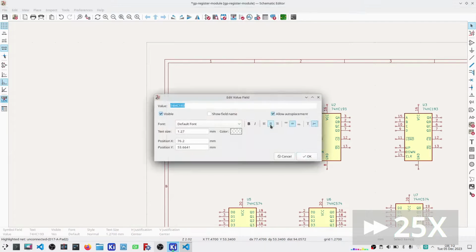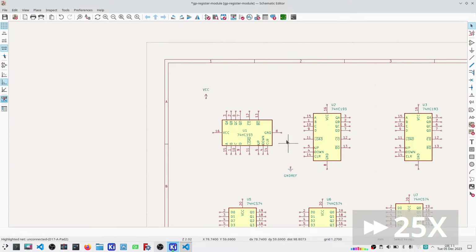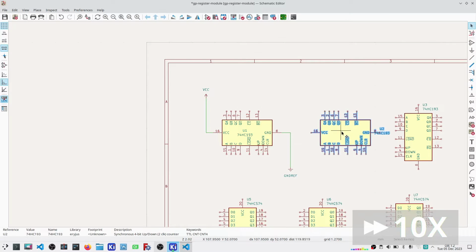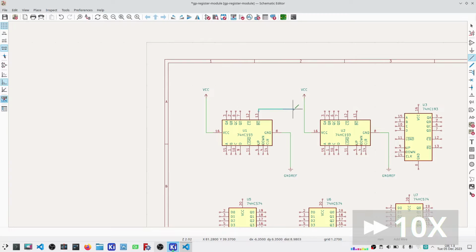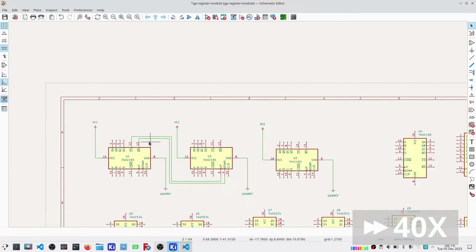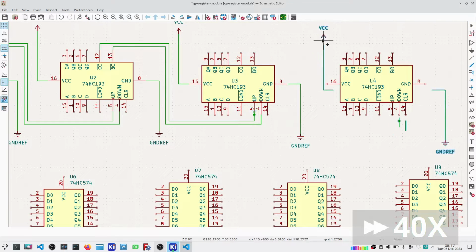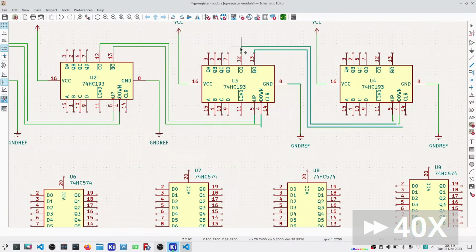The first thing to hook up are the counter ICs. Start with power and ground. I use copy and paste to fill in the second IC. After copying power and ground to the second IC, I add the borrow and carry outputs to the respective count down and up inputs. Then I can copy all those signals to the third IC. The first attempt at this was not brilliant, but the process improves as I go through this video.